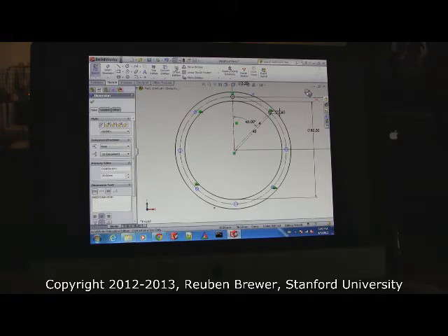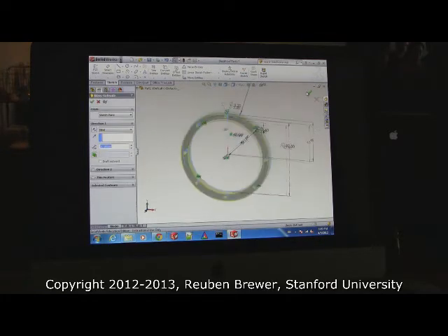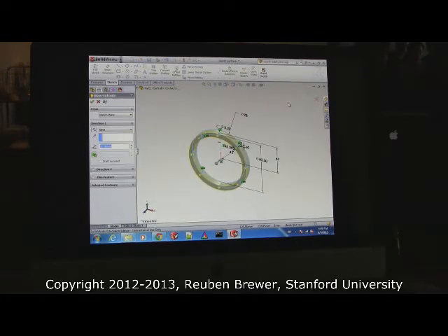Okay, so everybody press the purple button that looks like a pencil. Okay, now you see it's yellow, and you see how it extruded it out? It basically took the two-dimensional sketch and added a third dimension. This is how it always looks. If it doesn't look like that, it will barf at you, and it means that you screwed something up. Now, this number controls how big it is. See?